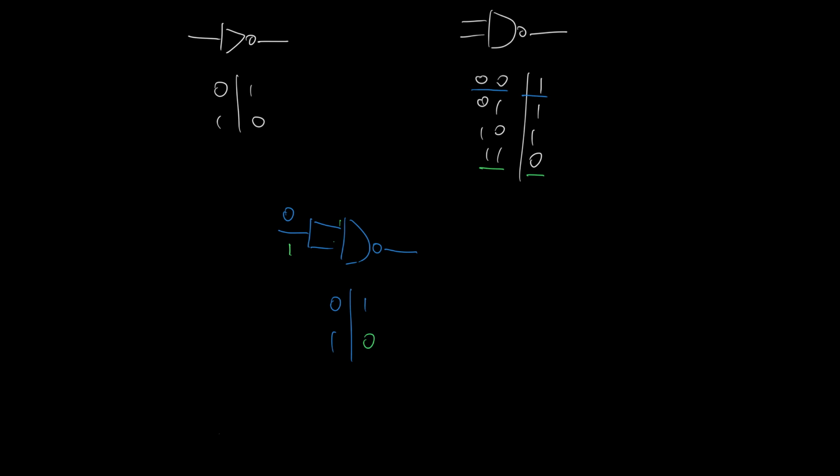And so it's a bit like before. These gates look very similar. I just have to rearrange these two inputs. I need 0, 0 to act like 1, 1. If I can somehow swap those around, then I can implement an OR gate using a NAND gate.